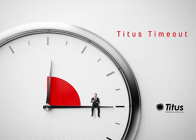I'm Jenny Abney-Civy, and this week I'm going to continue my discussion about HVAC at high altitudes and talk about water coils. So last week I covered that even though a CFM is a CFM at all altitudes and temperatures, the heat transfer capacity changes depending on the density of air. So I'm going to talk about altitude in today's podcast, but temperature will also affect density.